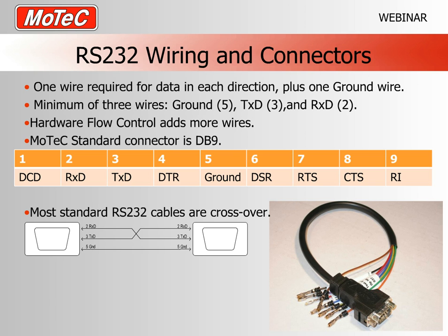If you buy a straight through DB9 cable, that will not normally work in an RS232 application, so that's why they're normally sold and labelled as serial cables, and they'll therefore have this crossover wiring as a standard thing.